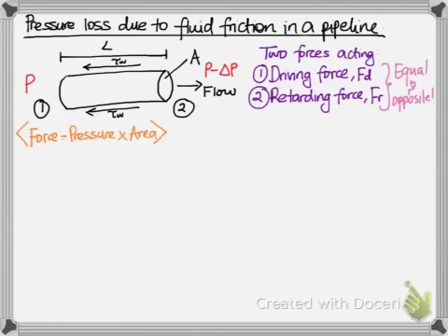It's this formula that we're going to exploit and expand in order to calculate the driving force. So let's start with FD, the driving force. The driving force will be equal to the pressure force at point 1 minus the pressure force at point 2, so we can call that F1 minus F2.